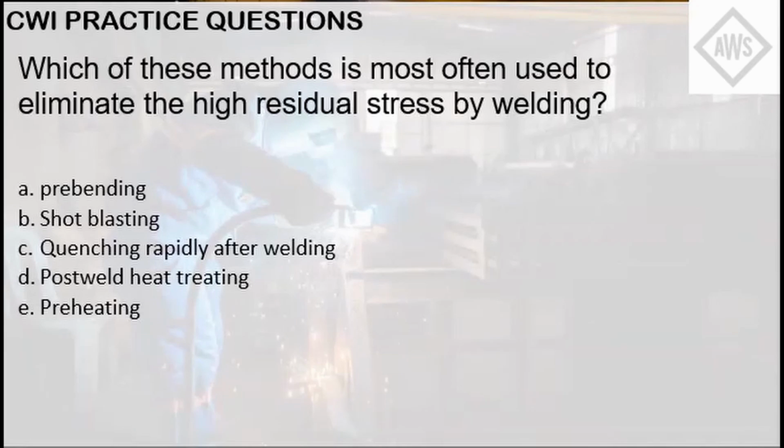Shot blasting, in the meantime, is a form of surface preparation technique used to remove debris and irregularities in the base metal. Some examples here are sandblasting. When you prepare a metal prior to welding or prior to painting, sometimes you need to sandblast it in order to remove the irregularities, debris, or an external coating that is undesirable prior to welding or repainting of that base metal.